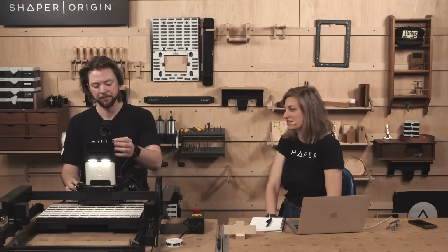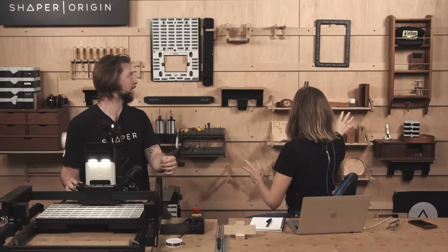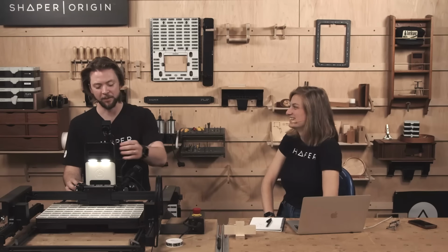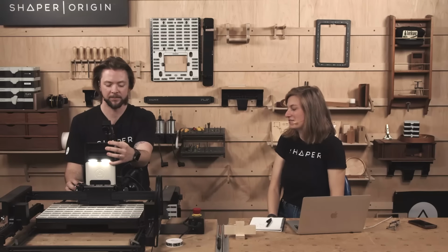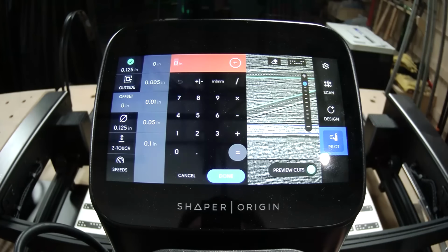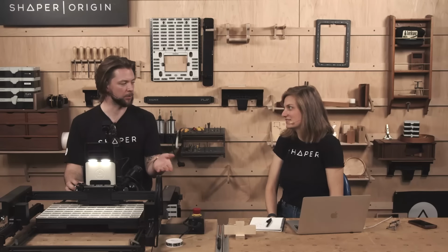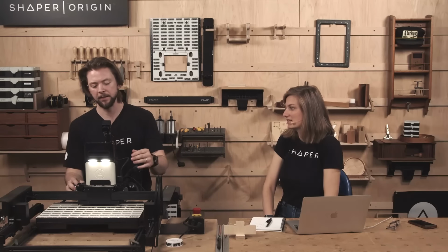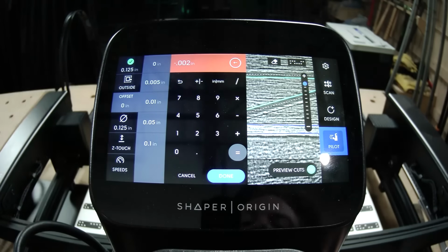Yeah, I guess we'll see how it feels when we're putting it together. I was looking back because I was looking for the marquetry we usually have up here, but I don't see it. Somebody probably used it as a demo somewhere else. But I imagine that would also be a moment where you would want those negative offsets. Totally. If it's just one thing, like, for example, a circle being inlaid into a piece of wood, cut the circle to 0, true to size. Right. Then a negative offset on the pocket, because that way you can dial that in. Something really small, -0.002 of an inch.